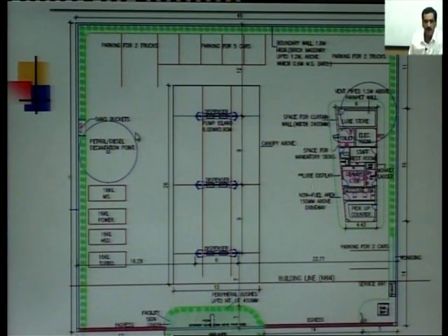So when we are going to have these tanks in an earth pit, the vehicles cannot move on top. So it will be placed at a corner, maybe somewhere over here if it's a typical plan. So these are placed over here, and our vehicles will not be moving onto those tanks. Beyond those tanks, we are going to have a curb wall or a curbing, which will be defining our traffic movement, our inlet or outlet traffic.